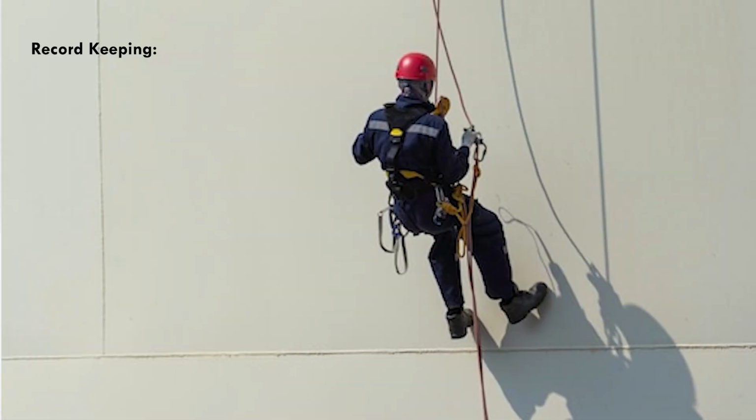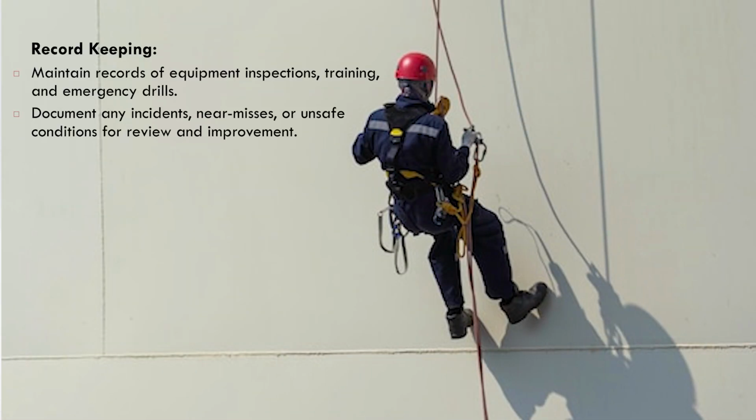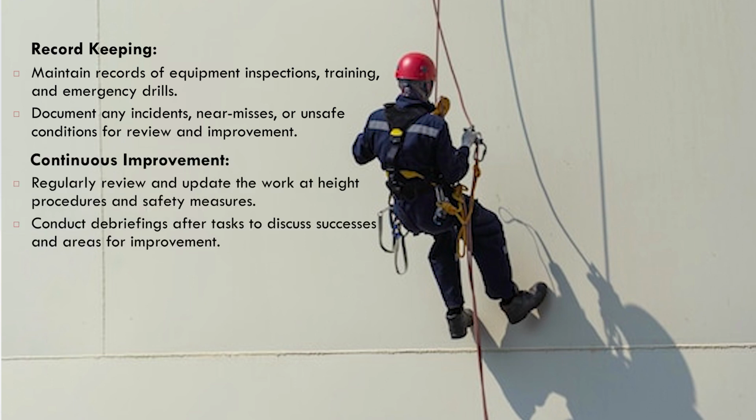Record keeping. Maintain records of equipment inspection, training and emergency drills. Document any incident, near miss or unsafe condition for review and improvement. Continuous improvement: regularly review and update the work at height procedures and safety measures. Conduct debriefing after the task to discuss successes and areas for improvement.